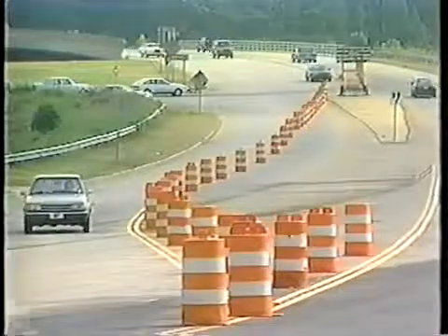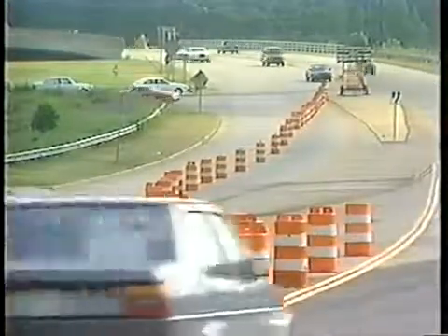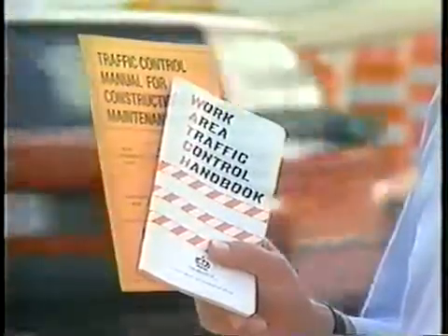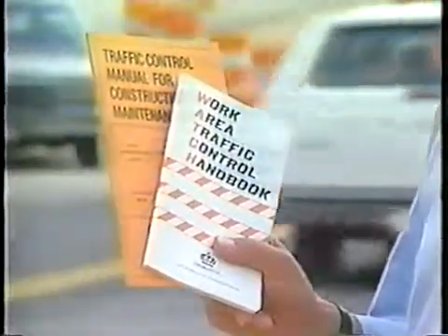We've reviewed the need for traffic control at work sites, examined the traffic control zones, and looked at the standard traffic control devices. Now we want to take a look at some typical applications of work zone traffic control. The various state and local supplements to the Manual on Uniform Traffic Control Devices provide detailed layouts in addition to those shown in the MUTCD. Unfortunately, it's not possible to demonstrate or illustrate all of the possible applications that you'll encounter in your work. Using your judgment and experience, you can adapt these typical layouts by modifying the dimensions in the various diagrams.